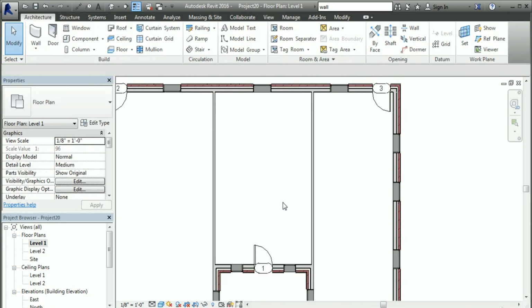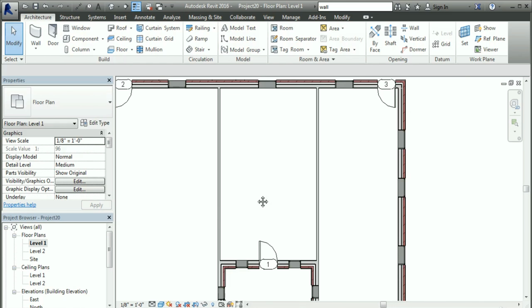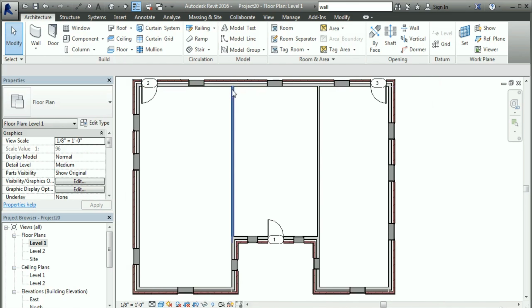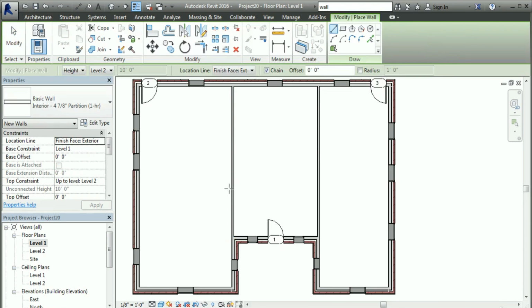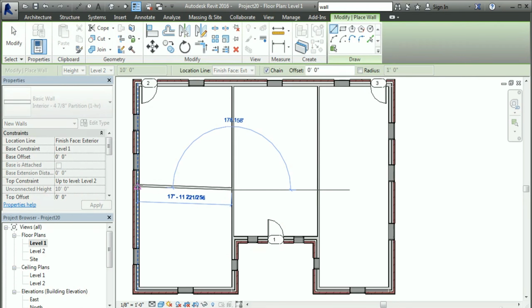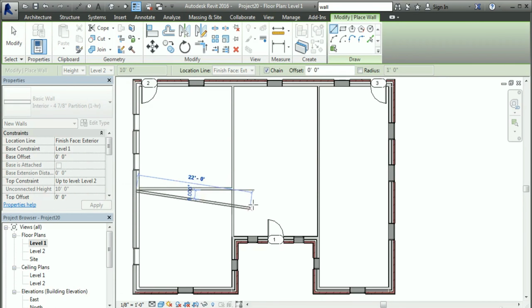We're going to do another wall. Let's see, we'll do a couple of horizontal walls as well. I'll pick the existing wall, and then I'll type CS or choose Create Similar, and we're going to add another one in here. And I'll just reach up, hit Escape.